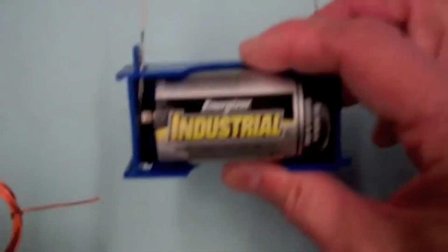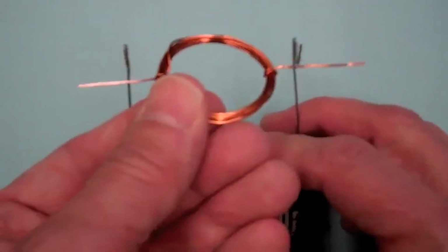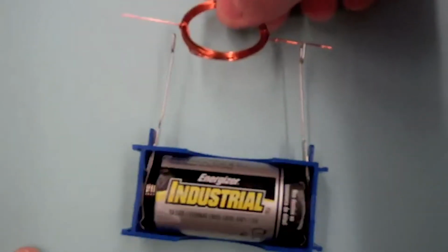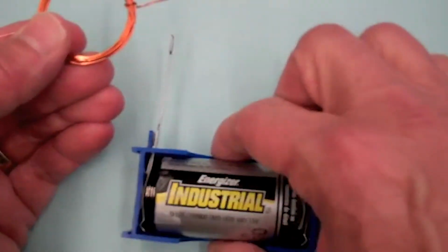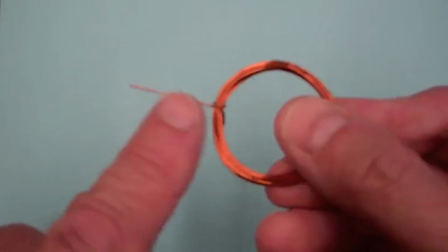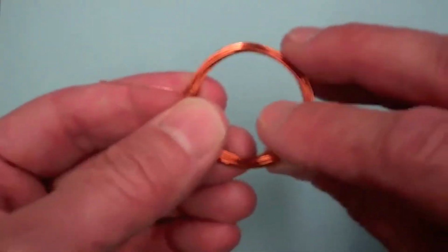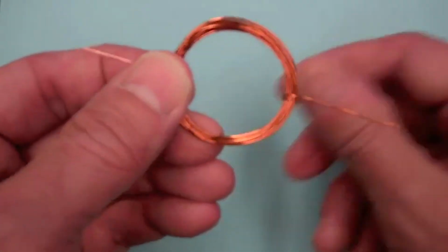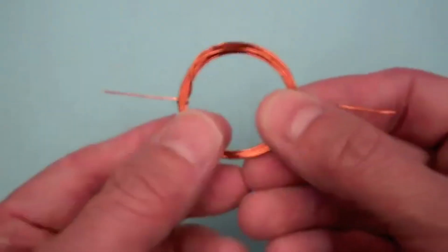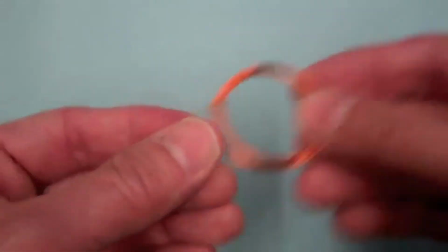Now what I have here is a battery with just a couple paper clips so that I can pass a current through this loop by laying it against these paper clips. Now I don't actually get commutation. What I've done is I've just removed the insulation on one side of the wire here, so that when it rotates and the magnetic dipole moments align, the current stops because now the insulation is touching the paper clip, and momentum will carry the loop around.